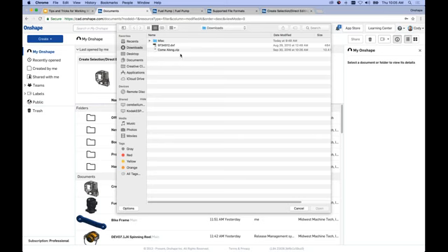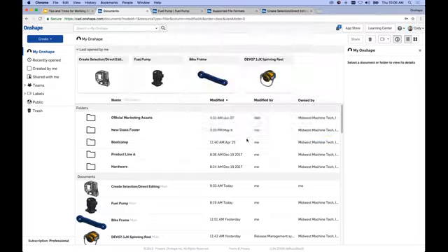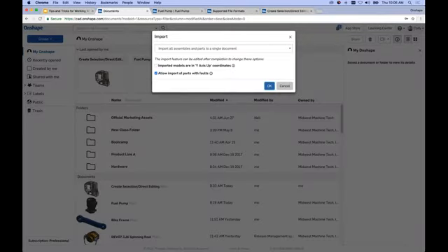But in this case, I have a zip file. This is a SolidWorks Pack and Go zip file that I'm importing into Onshape. So I hit open, I hit OK. I can choose any kind of import options that I'd like. Now, keep in mind, there are a few critical import options that you may want to consider. If the imported model comes with the y-axis up, as is the case in many CAD systems, you would want to check this.